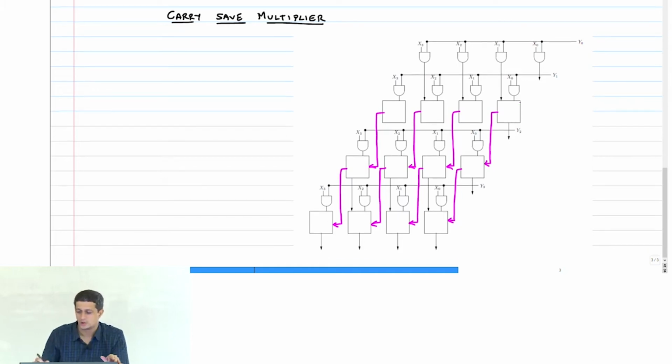Right? So now let's start filling out what should be my half adder, full adder. First row, all are only half adder because it's only the partial products. The two ANDs I'm going to add, that's all, right? Therefore, this is a half adder, half adder, half adder.